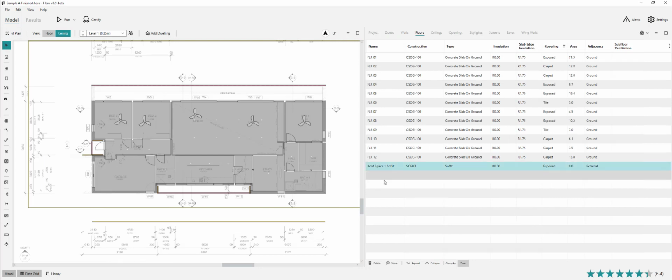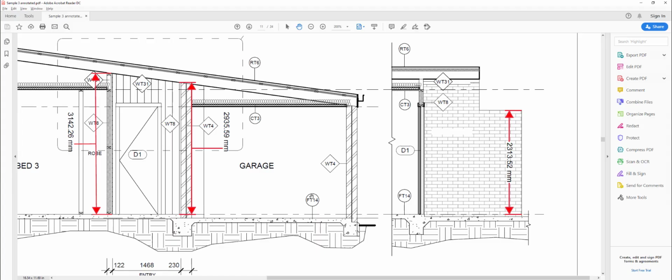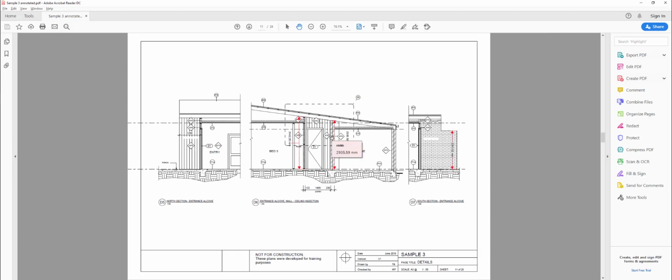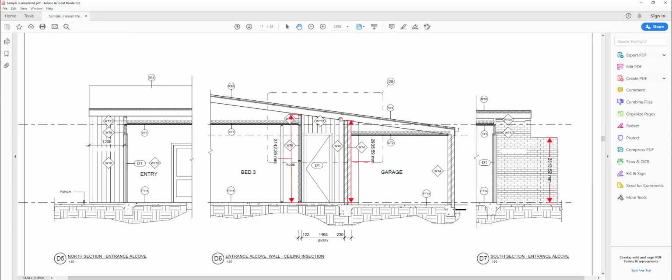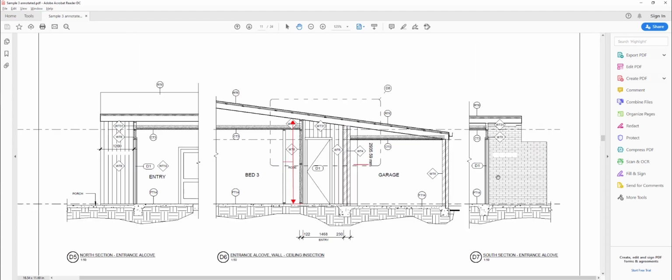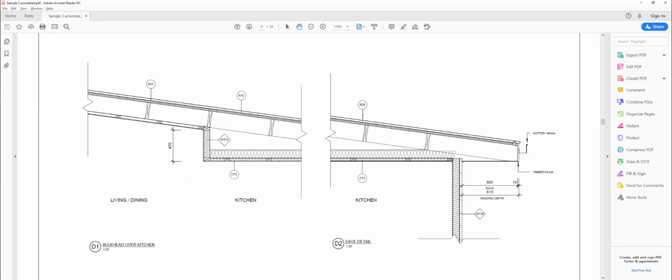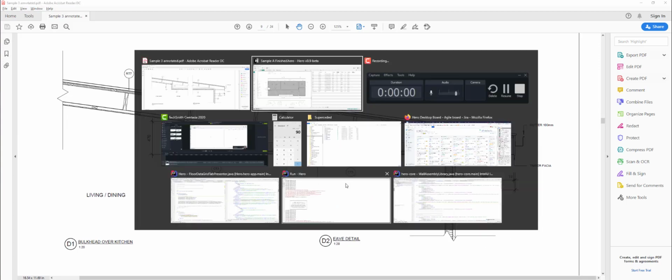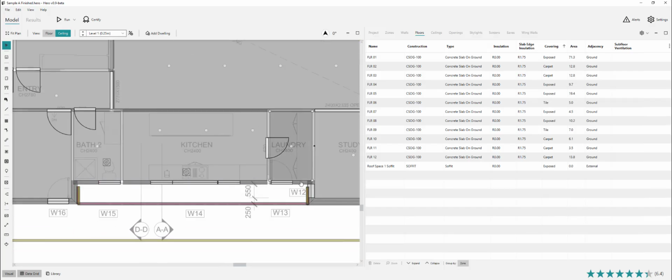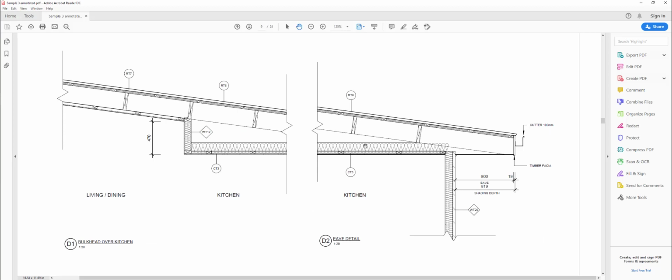The other element of this roof space zone that we need to be aware of is this soffit area, so we'd be going through our plans and making sure of that space. You can see here over the alcove there certainly isn't any roof space adjacency, but we might want to check whether over the southern end of the kitchen, this eave here on the back side of the kitchen could potentially be argued to be into the roof space of the dwelling. So we might want to add this uninsulated eave soffit into our model because there will be a heat transfer up here into the roof space.